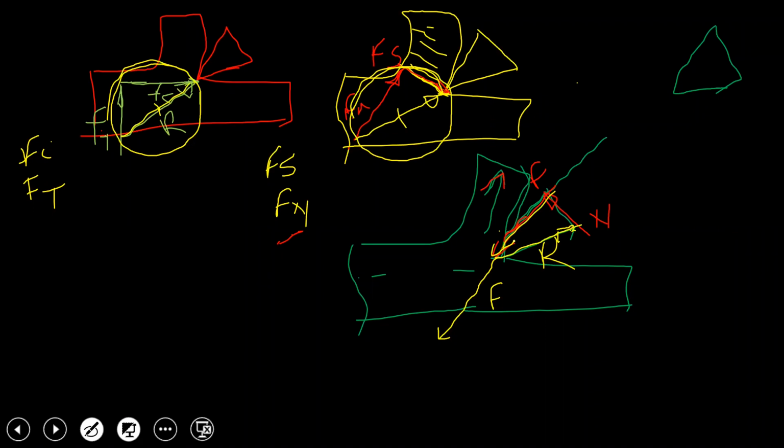Now I will draw this normal component in this direction. That would be perpendicular to frictional force. Okay, and now I will calculate the resultant of this F and N, and again that will lie in this position. So I will locate its midpoint and draw one circle. So again, all the forces will lie on the circumference of the circle. So this one we did for frictional force F and its normal N.